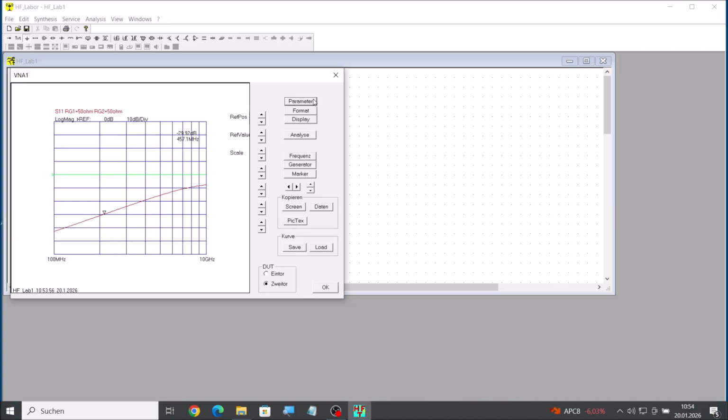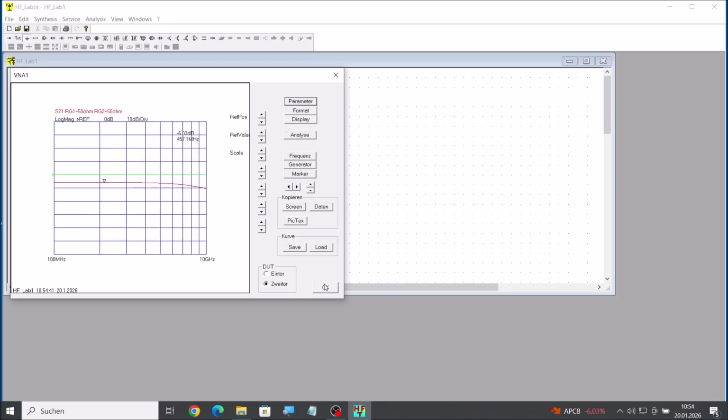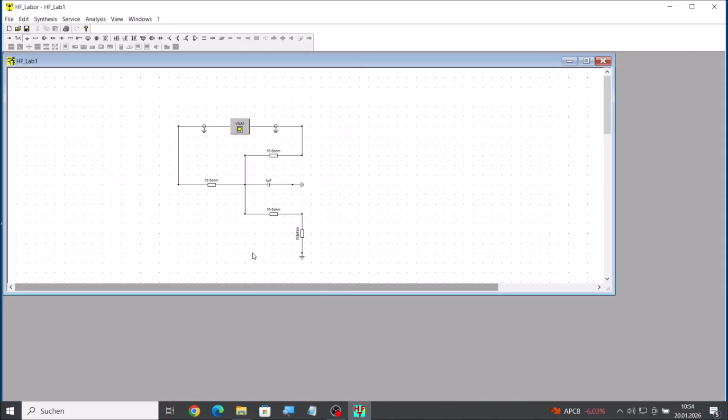So again, the parasitics of our circuit will of course change the frequency behavior, and to have a really realistic simulation we would have to include some parasitics of the resistors and also some parasitics, for example, of connectors and so on.